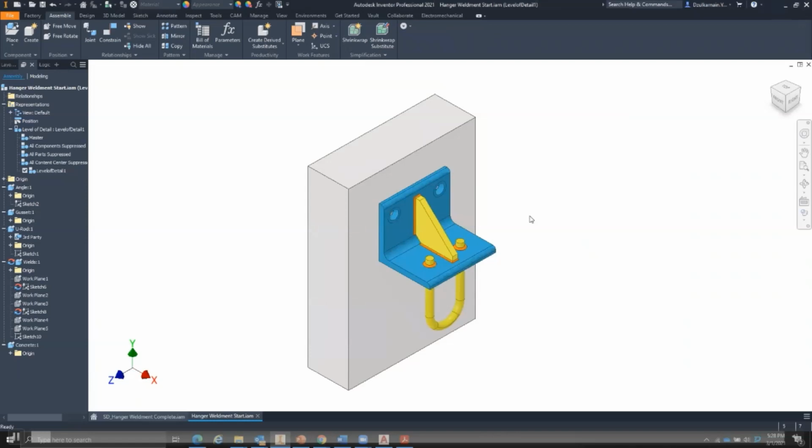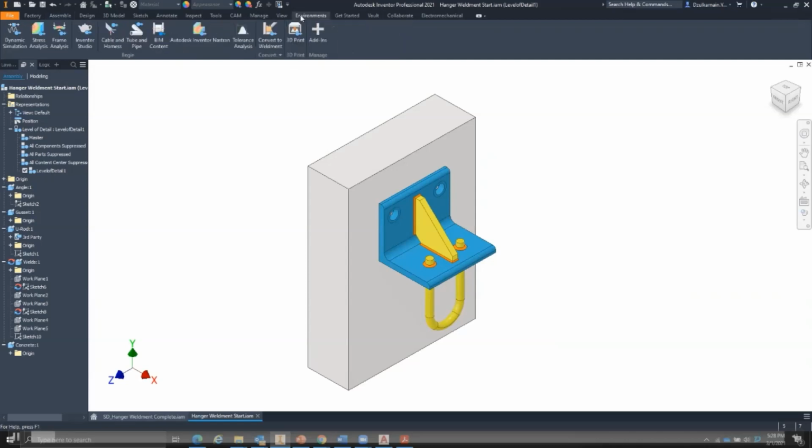Okay, so this is your typical Inventor interface. I believe you all are very familiar with this as well. To use Nastran, first of all you need to have a Nastran license. Let's say your customer is buying or you have PDMC, so you should have the Nastran license together. But the installer is separate, so you need to install Inventor first and then install Nastran.